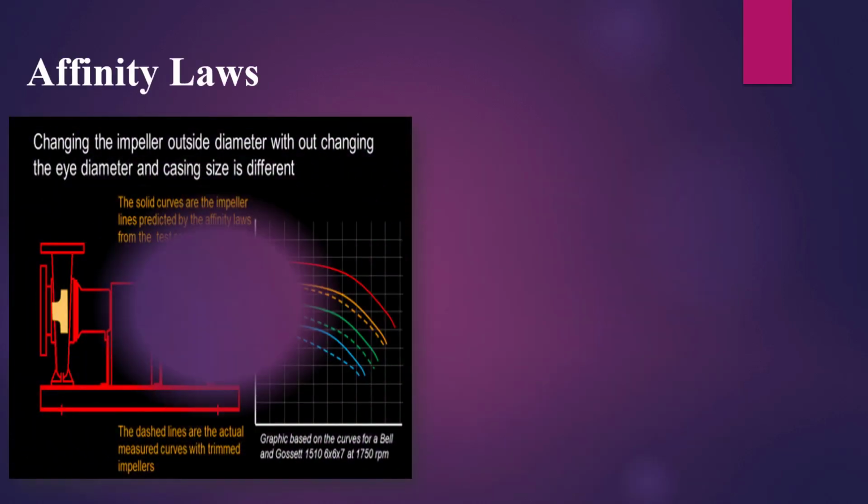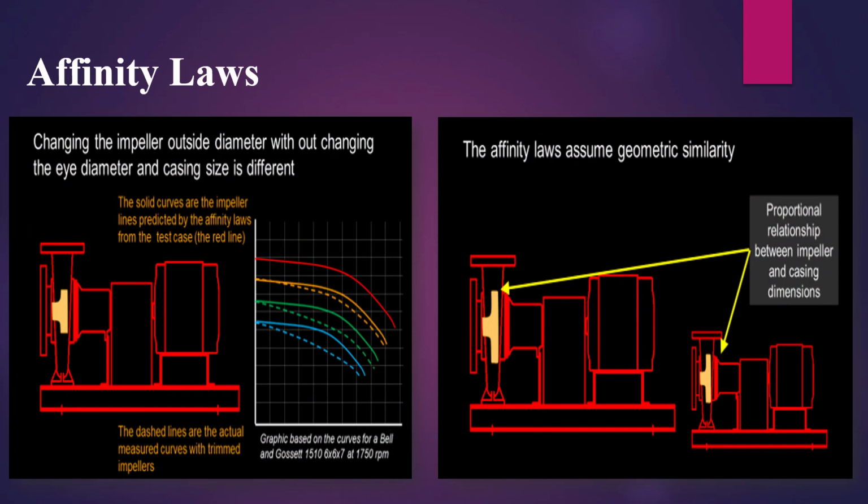To begin with, let's see how damaging speed control can be financially. You need to know a few simple physical laws in order to do this. These are called the affinity laws. Flow is the output from a device such as a fan, pump or compressor, expressed in cubic meters per second, or cubic feet per minute. It is proportional to the shaft speed of the motor. This means that with half the shaft speed, you get half the flow.